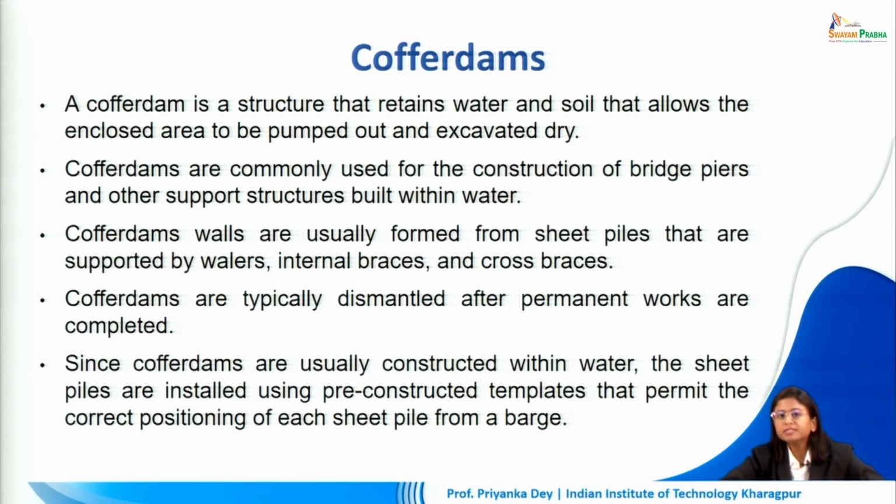So cofferdams are very useful if we are constructing bridge piers and other support structures within water. So let's say we have to do a bit of construction inside a water body. We're going to have to create an airtight, watertight, empty space on which we can do the construction. That's where cofferdams are going to be useful.